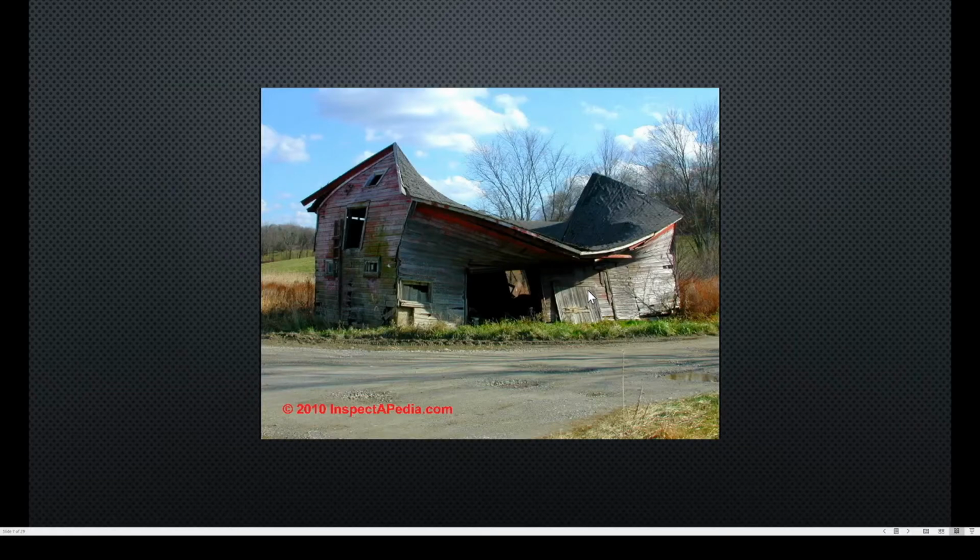The other thing about sagging roofs that I said, this is the most extreme example that I could find, and it shows how the roof sags down in the middle and the walls are forced outwards in the middle. The end gables are actually held in a nice triangle by all of the framing that's in here to hold them straight. They're pulled inwards, but they still sort of hold their triangular shape.